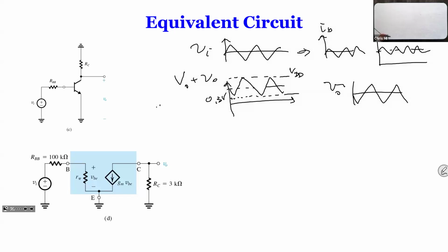So that's kind of your output range. So if your waveform is moving out of this, like more than that, it's not going to work for you. Now, if your biasing point is exactly in the middle, you can get a perfect waveform that reaches the boundaries at the output, but if your bias point is not in the middle, you could hit your boundary quicker on one side than the other side.